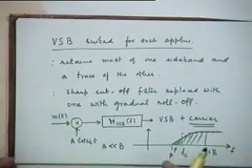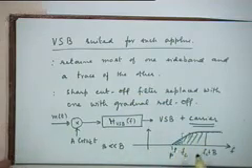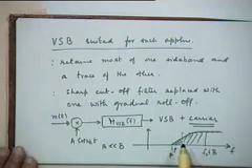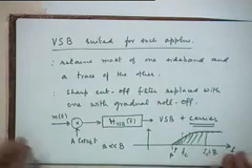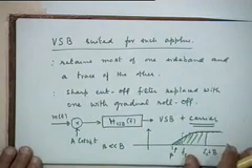I'm not getting into filter design. I'm getting into what should be the nature of the transfer function of such a filter, right, such that we are able to reconstruct our message signal back, because that's the ultimate requirement. The two requirements: one is we want to save the bandwidth, which we have done, right? Not by the whole amount of B, but by a fairly big amount, right? For example, for the TV signals, this could be, let's say, 500 kilohertz, as compared to 4.5 megahertz. This is still a good saving, right? And so on and so forth.